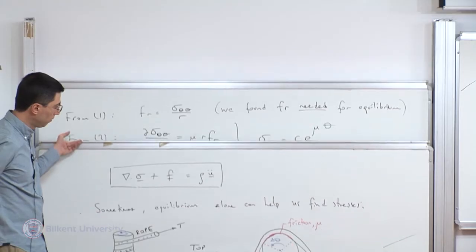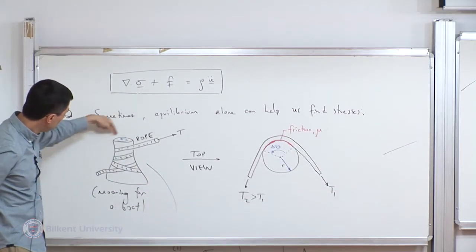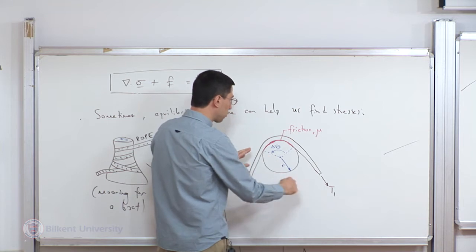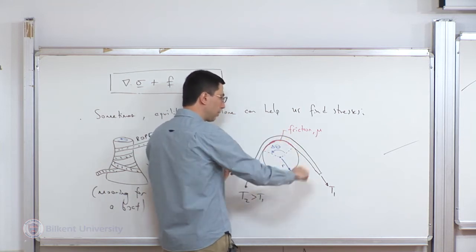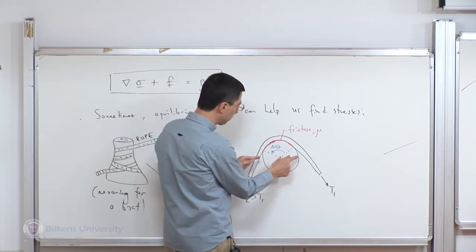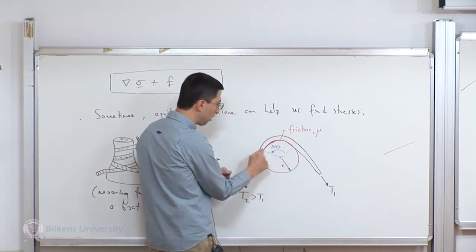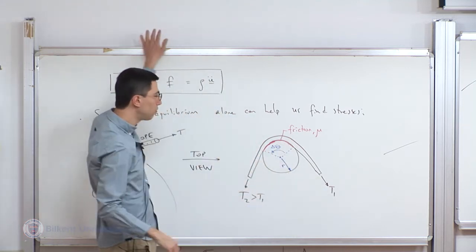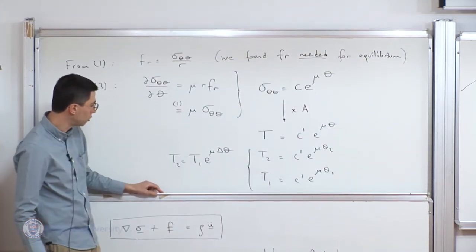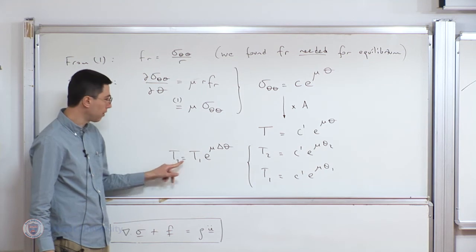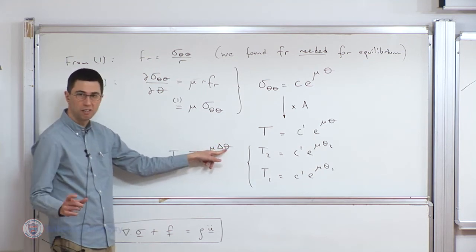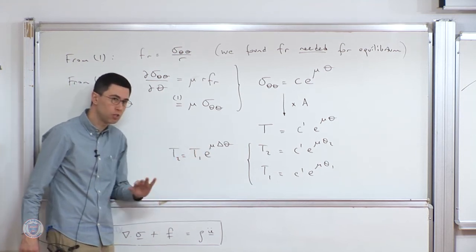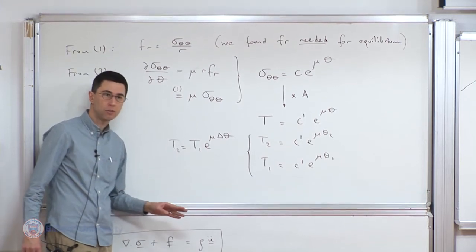Okay, so this was the problem, right? In principle, there are many turns. Eventually, we can think of the rope being constrained to just a plane of the cylinder, and it rotates as many times as we like. It doesn't matter, but just for analysis purposes, I took a section, a wedge from that rotation, T1 to T2, through a variation of delta theta, and there is friction. And now we find that due to the presence of the friction, the tension from one angle to the other, through a simple rotation of delta theta, is rising exponentially fast, right? So due to the presence of friction. No friction, as we expect, nothing happens, right? The tension remains the same.